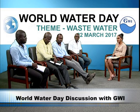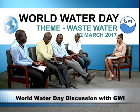And therefore, to get rid of these contaminants in the groundwater, different processes are required. So it's not necessarily a one process fits all, but a specific process where it involves aeration, sedimentation, filtration, ultimately disinfection. Now, persons would see the aeration in action quite a lot without probably even recognizing it. If you pass on the back road at the treatment plant there, on the east bank, also on the east coast and many other areas, you would see water flowing down.